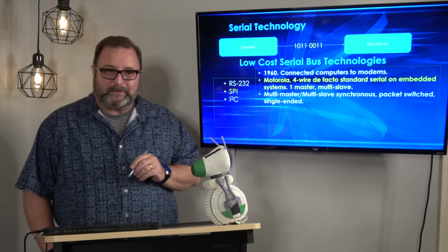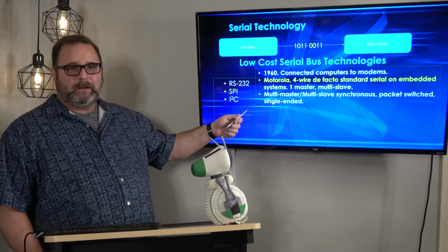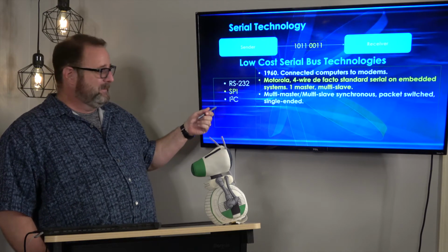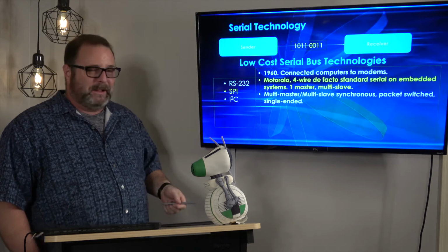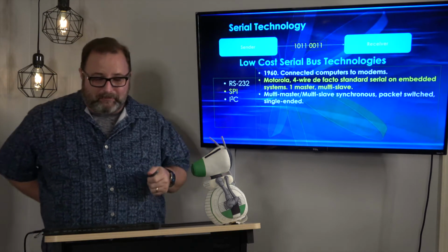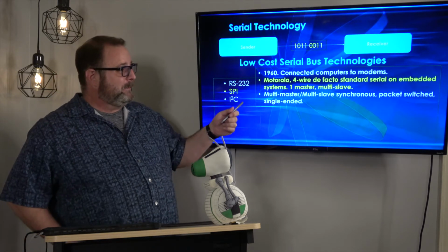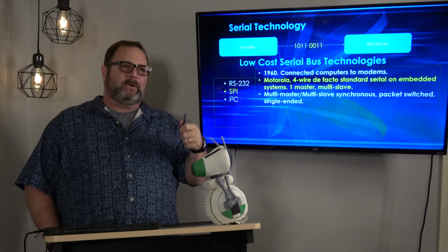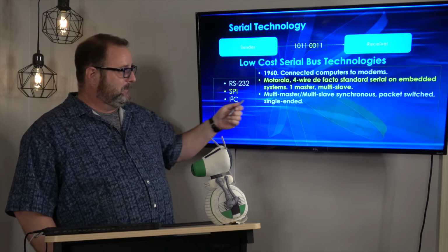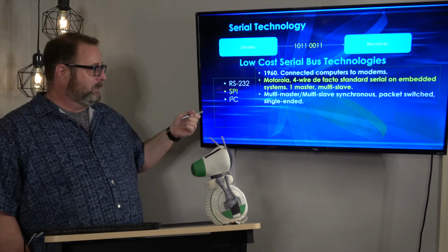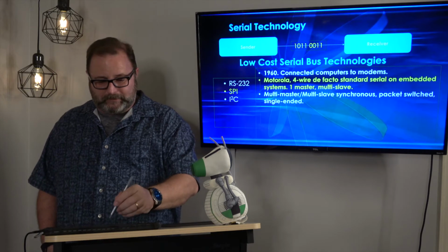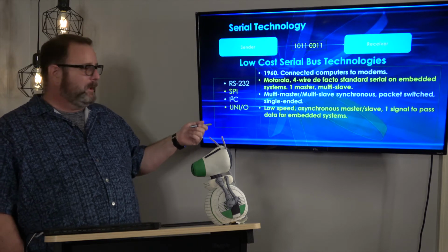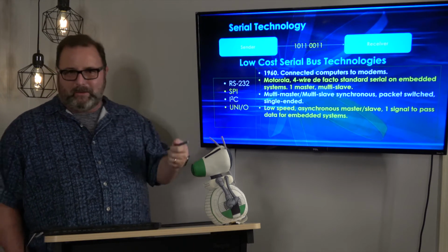All right, I2C. Sometimes you'll see it written I2C, probably because people don't know where the superscript is in Word, but it's I²C. It's multi-master, multi-slave, so you can have multiple masters, it's synchronous, and it's packet switched. So the information goes into packets, not totally dissimilar to what we do with internet packets. It's information packets that are controlled over I2C. So that's another way we can do it. And I'm not sure how you say this, whether it's UNIO, but it's UNIO.